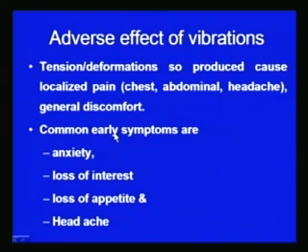The common symptoms which are experienced under the effect of the vibrations are anxiety, loss of interest, loss of appetite, and headache. So, the adverse effect of the vibrations on the human being appears in the form of pains, loss of interest, loss of appetite, headache, and anxiety. To reduce these adverse effects on the operator, the vibrations should be isolated, so that the worker can perform for long without much need of a break.